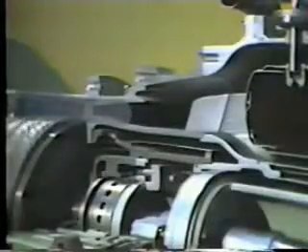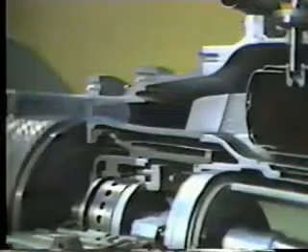First, the moving rotor blades add energy to the air and force it along to the adjacent stators. You remember that the air path along the compressor's length is decreasing in volume. Let's look very closely at the space between one set of rotors and stators. Here, the shape of the air path is decreasing. In fact, we have a miniature nozzle. This causes the velocity to rise slightly before the air enters the next set of blades. So the nozzle effect is the second way that air velocity is maintained.